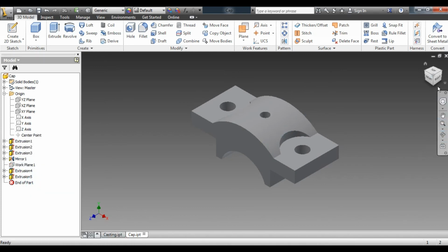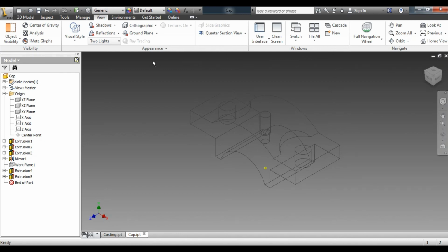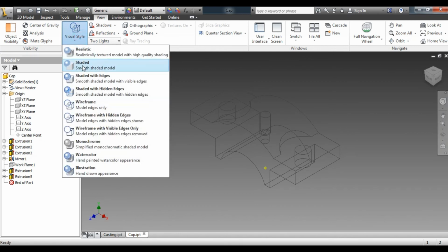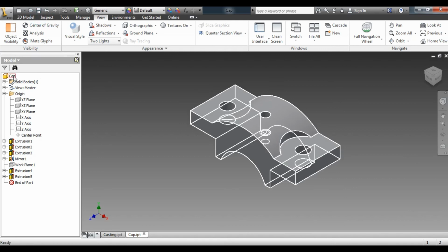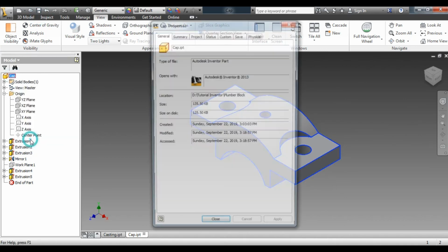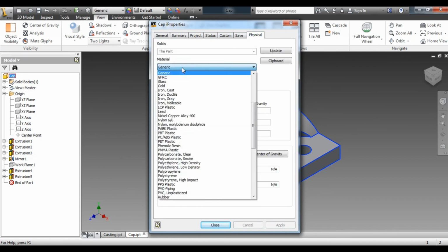Now I will remove the visibility and show you that in the wireframe mode. So this is your actual plane. Once I convert to solid modeling, I'll save the file first. Next I'll give the material, and we know from the material discussed below that it is cast iron.